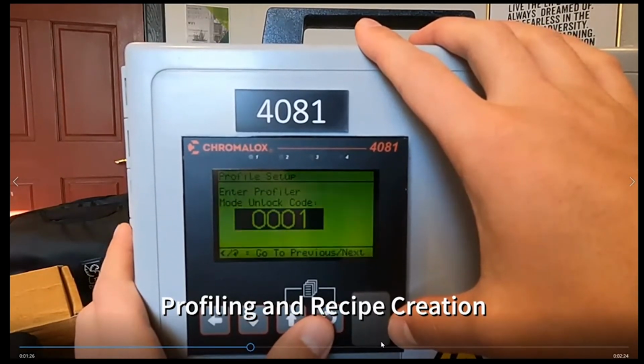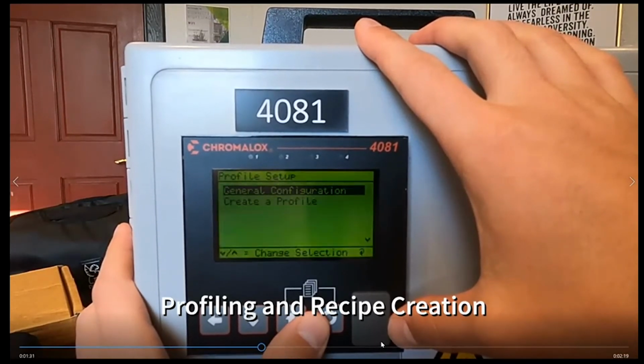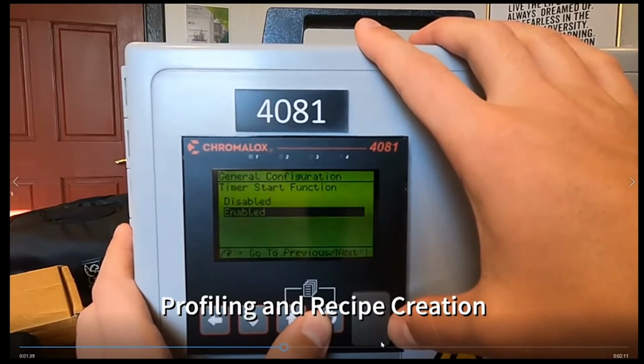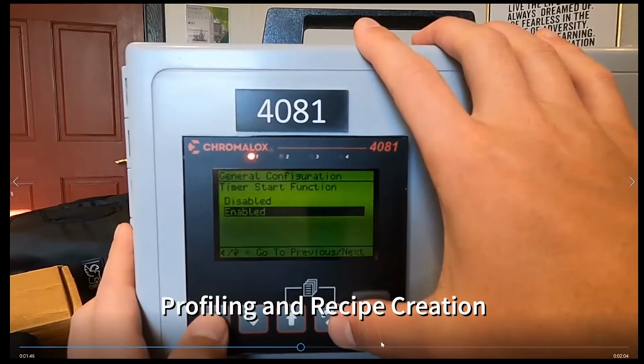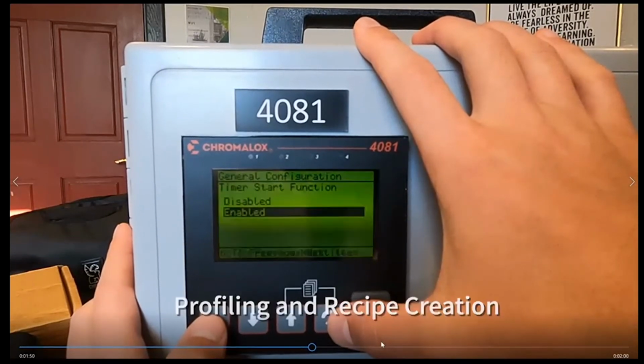But it also has the capability, talking about this one being a more advanced controller, of what we call profiling and recipes. Basically there's 255 segments, meaning there's 255 different points where you can do ramp soak. You maybe have to be at an X temperature, 100 for 20 seconds, and then move it up. These are really intricate processes that this controller is capable of running.